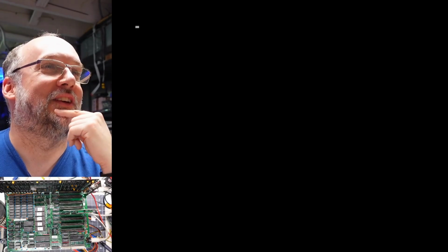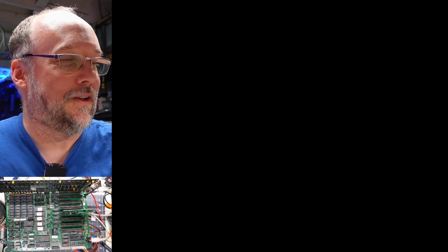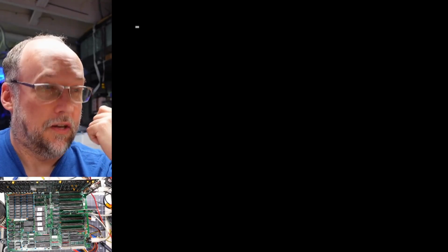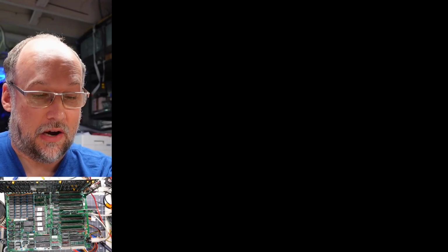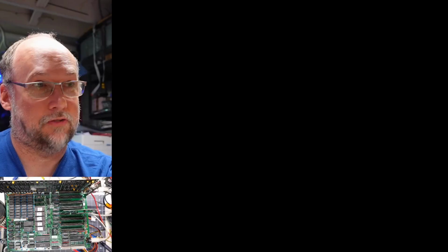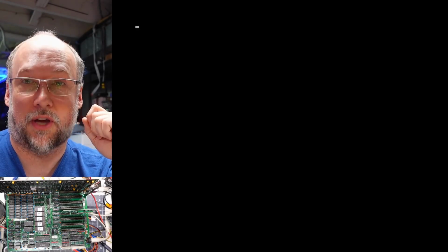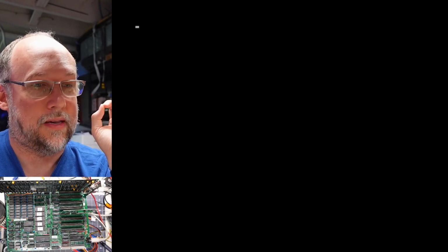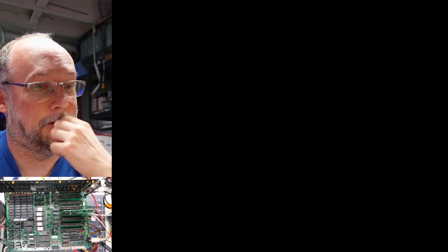Okay, we have a little bit of an issue here. It initialized the card, but we're not getting any actual updates here. I think what we're seeing here is purely a software issue too. This is not a hardware problem. This is just the way the software is written, expecting that status register to do something on that particular bit, and now it doesn't. It's just grounded all the time. So it actually thinks that the video is never enabled. It's probably why it's just sitting here waiting now.